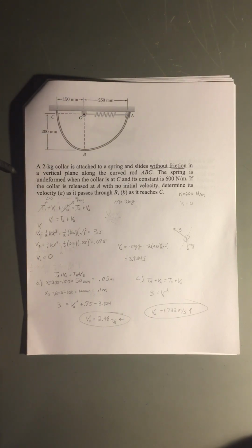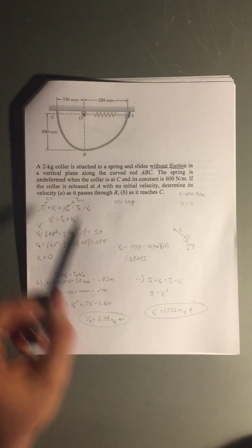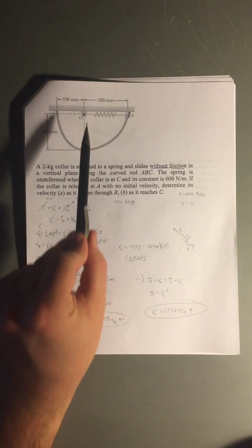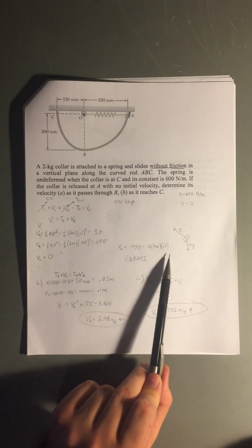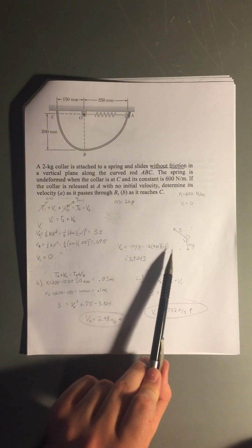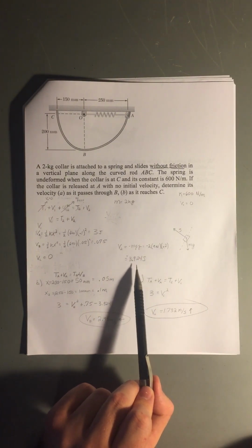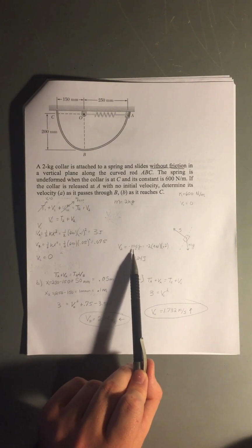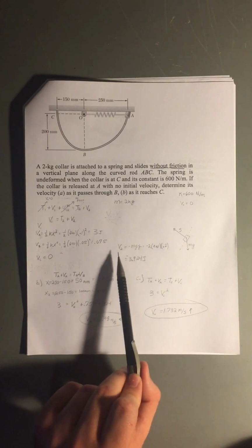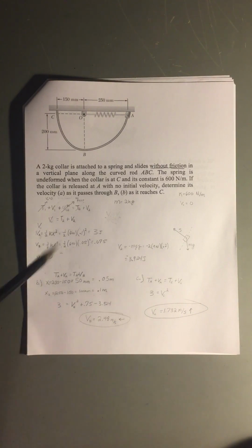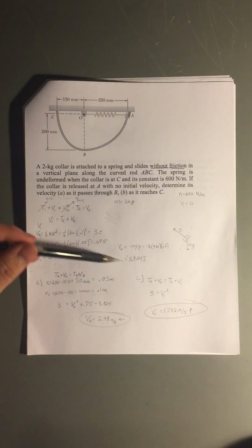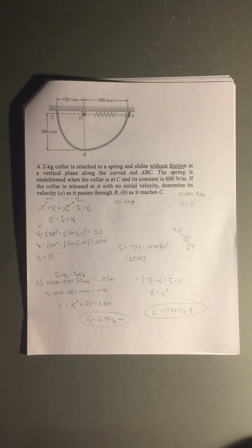And then the difference here, so this is 0.2 at B, and so calculating that, the difference between B and the origin is 0.2 meters. And then we know our mass was given to us, and we know gravity, and so we can calculate the potential from gravity there. It comes to this negative 3.924 joules. And then we have everything we need to plug into our formula.